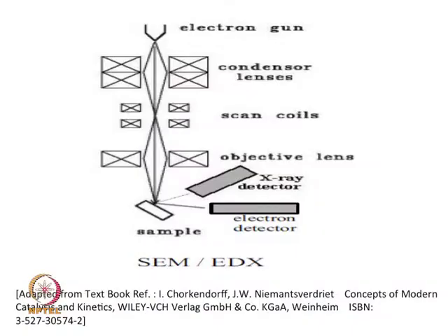This is just a picture where you have a source of energy beam, the electron gun, right, and there are condenser lenses to get a monoenergetic beam, and then the scan coil, which passes through the objective lens. So the sample is placed here, right. In TEM you place the sample somewhere here, but here the sample is placed here. So the diffraction comes, which may be, if it is X-ray, then an X-ray detector like EDX, or an electron detector.